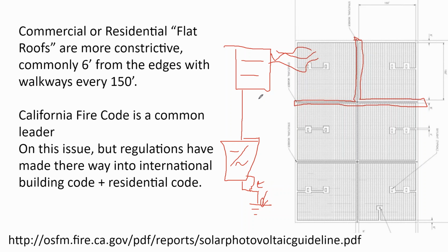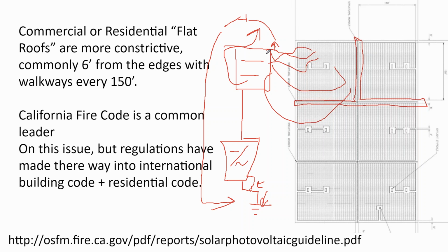And what would happen, and I'm not going to get into the details of it, but under a very weird circumstance, you could have one circuit on the rooftop ground faulting to ground and raising the voltage of this ground and not causing the ground fault detection system to work. And then all of a sudden you get all of the circuits of the array feeding into that ground fault, and it starts a fire on the roof and burns the building down.